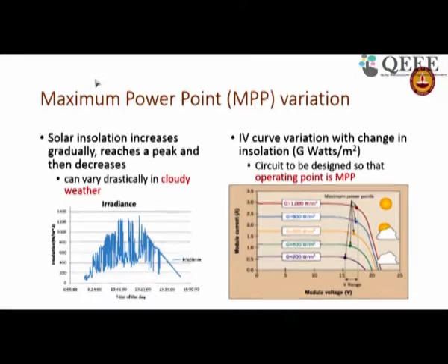You are suddenly adding losses. Number two, not only are you adding losses, you are also adding a point of failure. You are adding costs. The whole idea of moving to DC was that solar is DC, so keep it in DC form. Therefore, a slogan will not do. Conceptually it is very good, but how do you synchronize a changing-voltage DC solar line with what the loads want? I think this is one of the challenges. I'm not going to completely present this, but these are the challenges that we need to overcome.